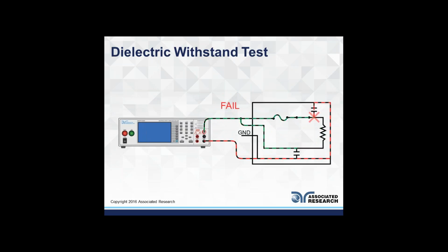By breakdown, we mean that applying high voltage to your product results in an arc and a really high flow of current through the capacitor that you created. This indicates that the unit was not able to withstand the voltage applied to it and broke down under that condition. This would be a fail according to the standards.